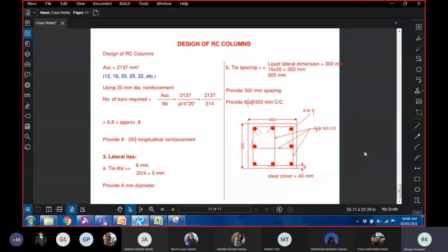That's a good question. The concept of an over reinforced section is a concept that we studied in beams, where we say that if a beam is over reinforced, it might have a brittle failure, and that is the reason we should never over reinforce. We should never have an over reinforced section in beams. In beams, the failure could be ductile or brittle. If it's an under reinforced beam, the failure would be ductile. If it's an over reinforced beam, the failure would be brittle.